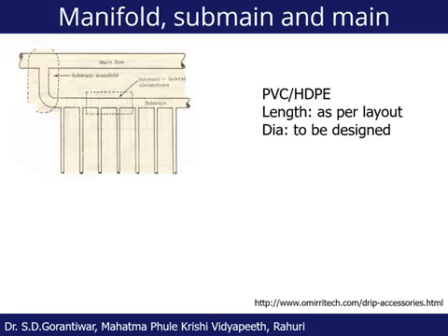The next is manifold, submain and main. I have already explained what the position of manifold, submain and main is. So here it is again shown. Normally manifold, submain and main are of PVC material or HDPE material. Only one caution is to be taken: when we use PVC material, then the manifold needs to be buried in the soil.